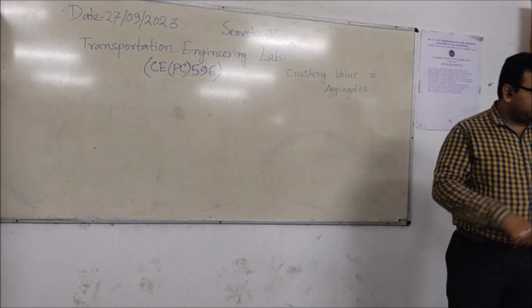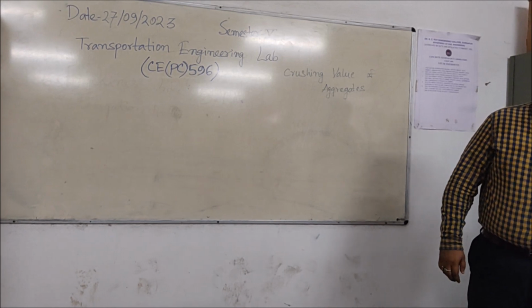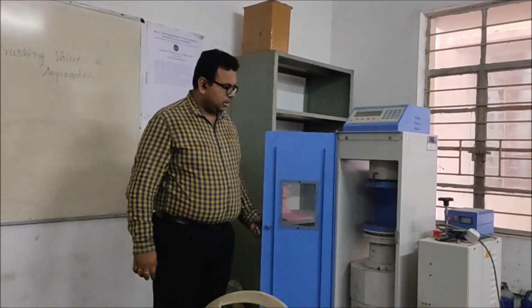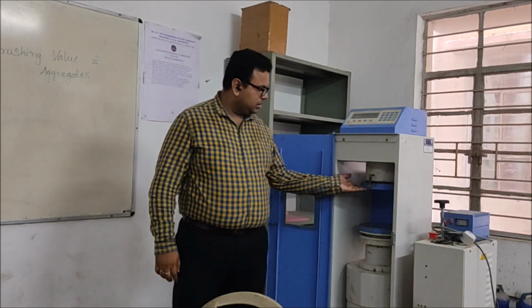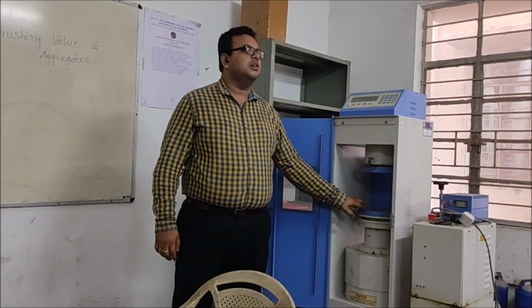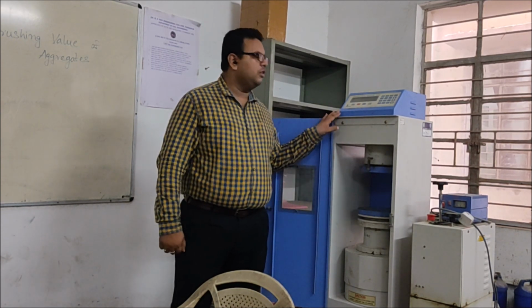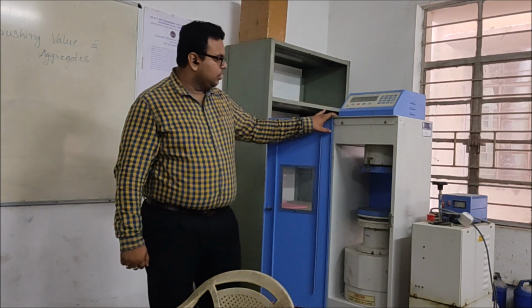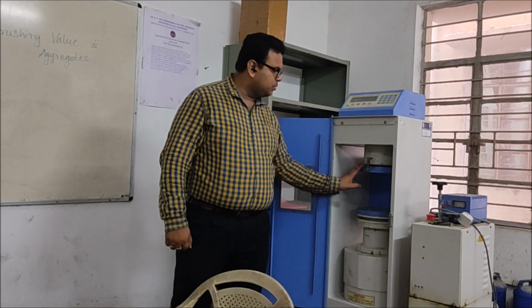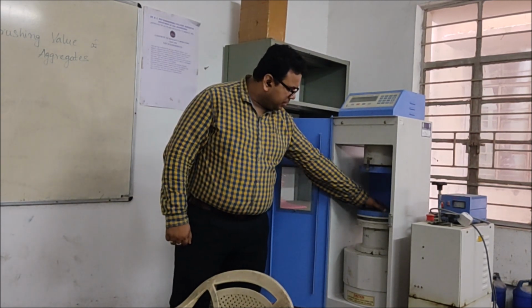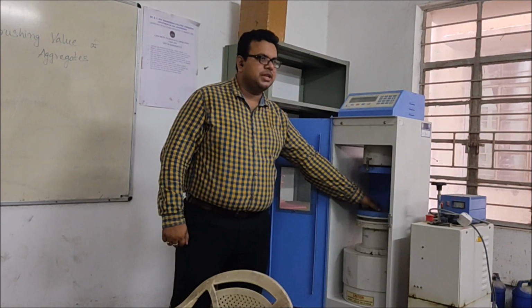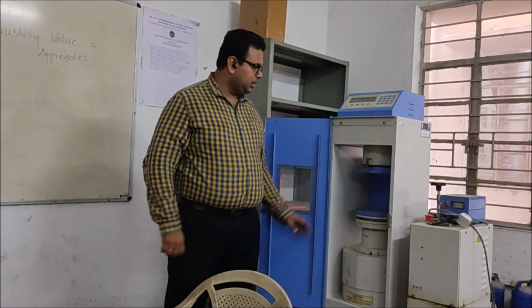In our case, after the sample is prepared, we will use this instrument. This arrangement is also used for aggregates and for testing the compressive strength of concrete cubes. Here, this base is where the sample will be placed, and upon it some load will be applied with the help of a clamp.